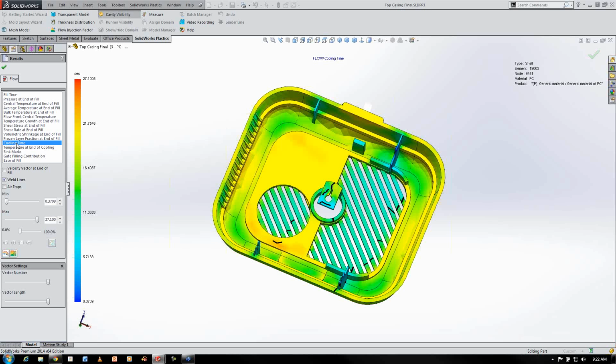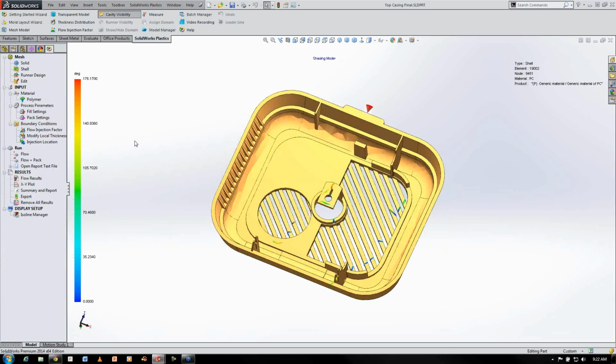We've kind of, I guess I'd say, optimized the wall thickness. At least we're better than where we began. But we still have to deal with all of the backfilling on the ribs and all of the potential weld line defects on that area of the geometry. So the first part of our analysis here, I'd say, is more or less complete, kind of using plastics to dial in the SolidWorks wall thickness to really refine the geometry in order to optimize the filling and making sure that cooling time is acceptable. There are more things that we could do, but I'd say that's a good first example here.